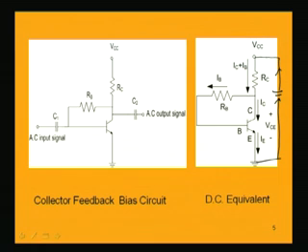The current which is through this resistance RC has to be then definitely the same current I, IC plus IB. So, this completes the outgoing current from the source and the entering current into the source. So, that two are equal. That is why the current which is seen here is IC plus IB, or that is equal to IE.